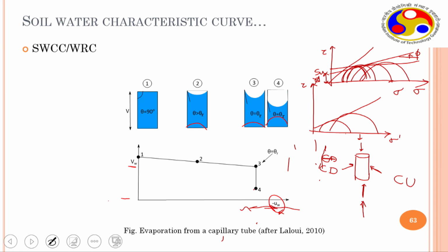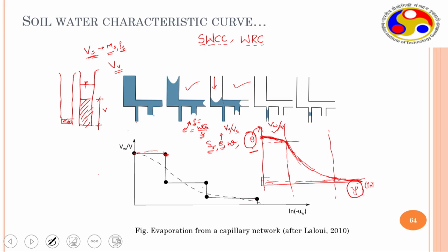They may have a relation something like this. But in case of soils, any heterogeneous material having heterogeneous pores all across distributed, you may have a relation something like this, right? S curve. Your particle size distribution curve, any curves you take in soil mechanics, they follow the same trend. So essentially, even effective stress versus void ratio, the relationship looks similar, right?